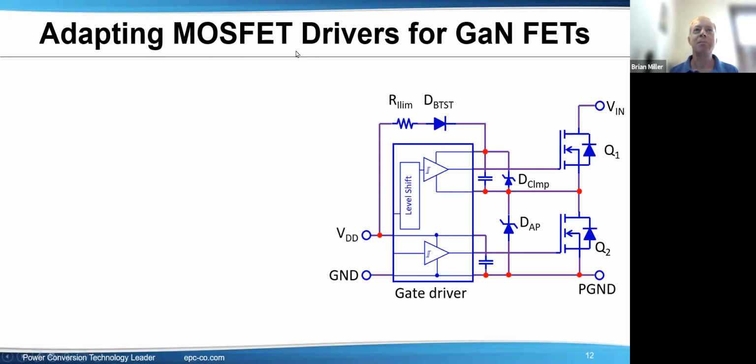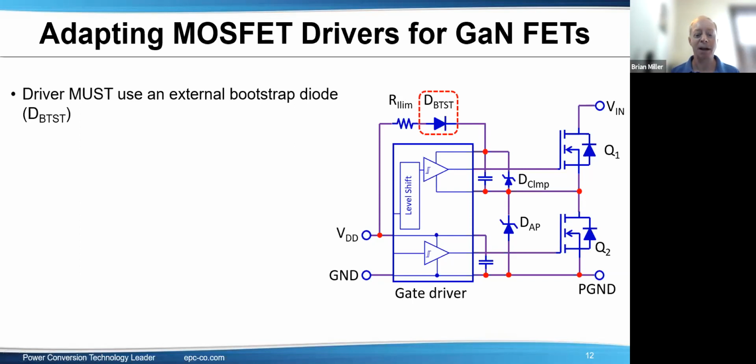Another topic is adopting MOSFET drivers for GaN FETs. And there are all kinds of situations. There could be specialty ones, whether it's built into a controller, or something that has to be used for one reason or another. And the question comes up quite a bit: can you use some MOSFET drivers for GaN FETs? Is there a way to just adjust things? And the answer is a solid maybe. In many cases, the answer is yes. So let's go through a few conditions here.